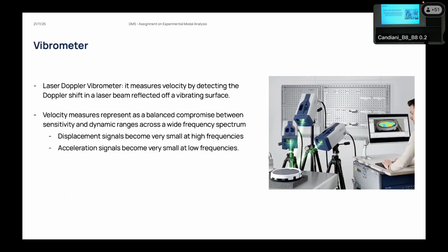As I was saying before, there are lots of possibilities to measure vibration on a structure. Usually accelerometers are very commonly used in much of the monitoring campaigns you can see, I think the most, outside. And this is because usually they allow for a good resolution of the response you can get. You are reading accelerations that you can integrate to obtain displacement.